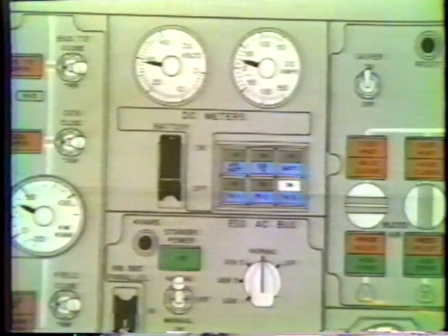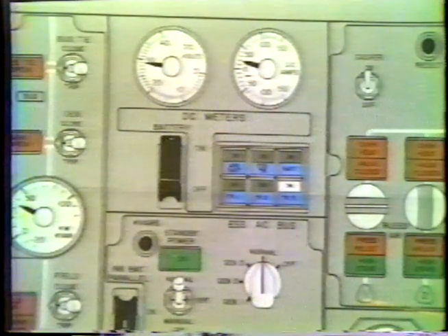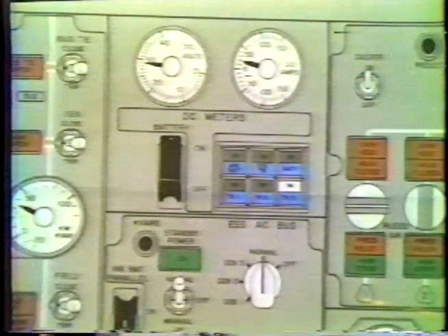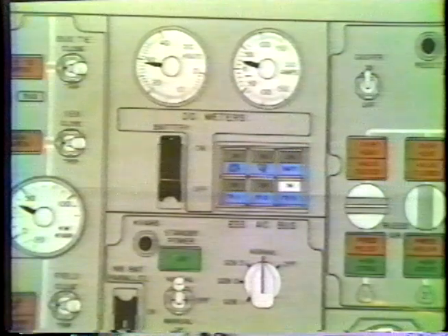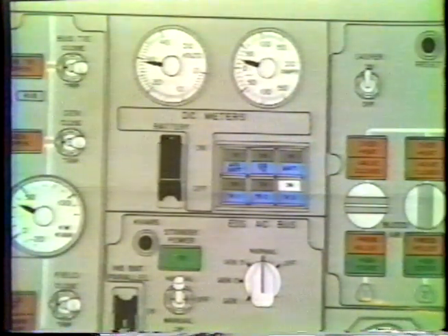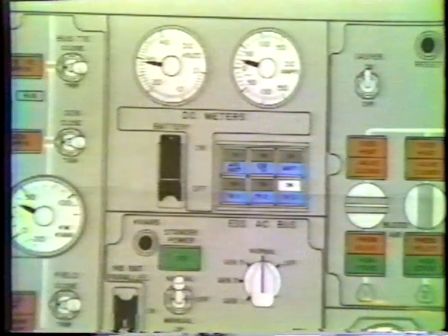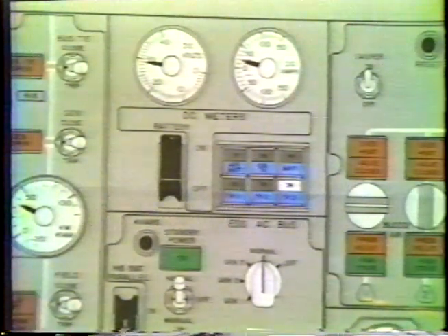And this would indicate the battery drain. Boeing indicates that the battery should be available with loss of all generators for a minimum of 30 minutes. However, one of the items that is on that battery bus is the #1 COM transceiver. And if you're making radio reports, every time you use the radio, you're going to reduce the amount of time that that battery is available. So it could be considerably less than 30 minutes if you're using radio a lot.